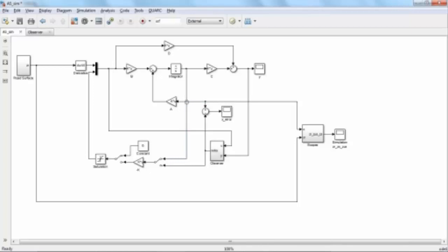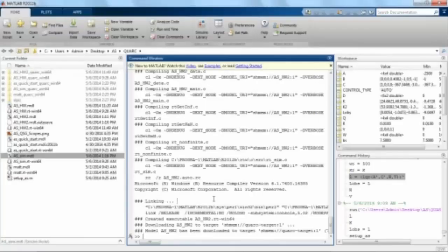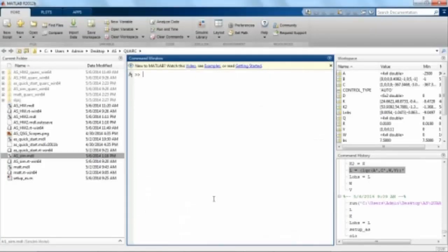So I plug into the state space representation right here and extract all the system states. Note that this is something I can do easily in Simulink or LabVIEW, but in real life this is not as easy. This is just to show you how nicely I can do this in simulation. Now in MATLAB, let's say our gain is called K3. If our system matrices are known, we can use LQR with our A matrix, our B matrix, a weighting matrix Q that I already have in the workspace, and a weighting matrix R to have all the parameters for our Riccati equations.